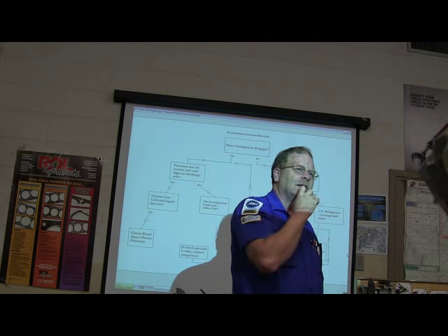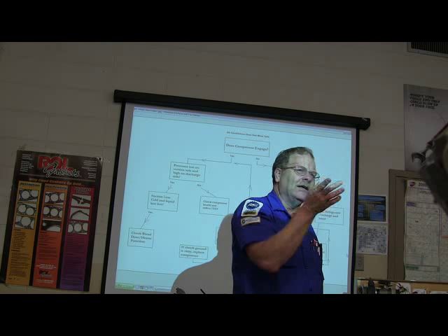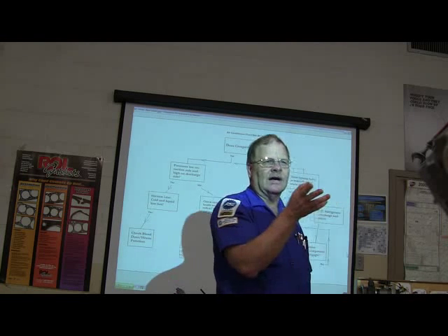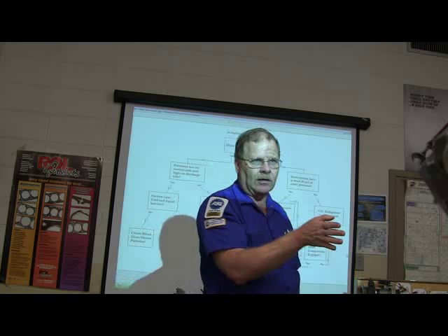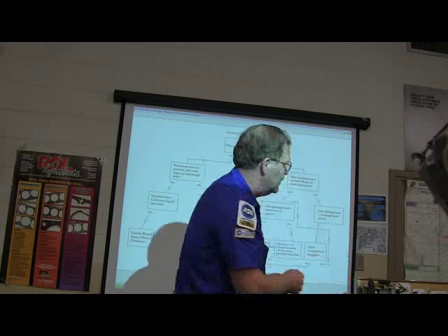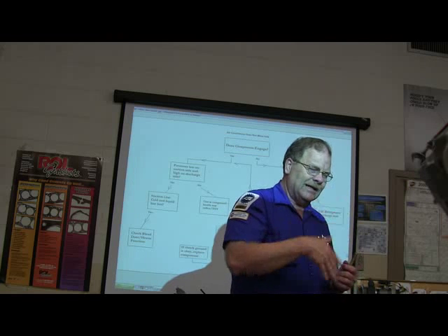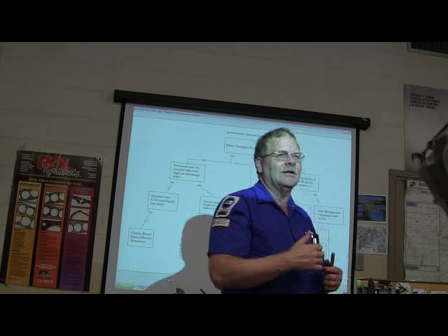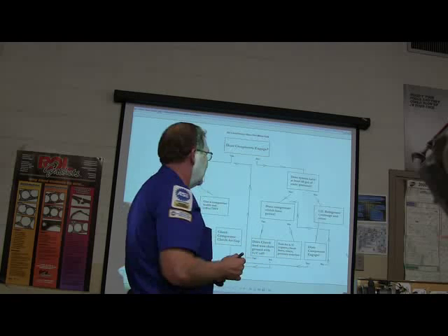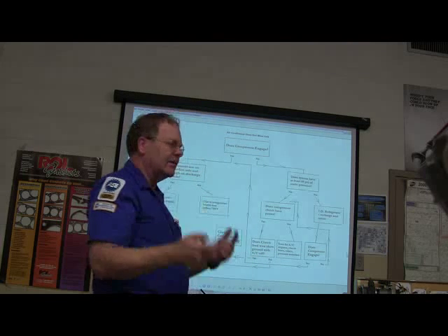Though, interruption of power somewhere. Well, basically, you've got a cut wire, or you've got a bad compressor clutch coil, or you've got a bad ground on the other side of the clutch coil. Seen that before. Seen the wires get over against the belt, and it chopped the ground that was feeding the compressor clutch. A Buick one time we had in here. So you've got to be able to think clearly enough to do this.